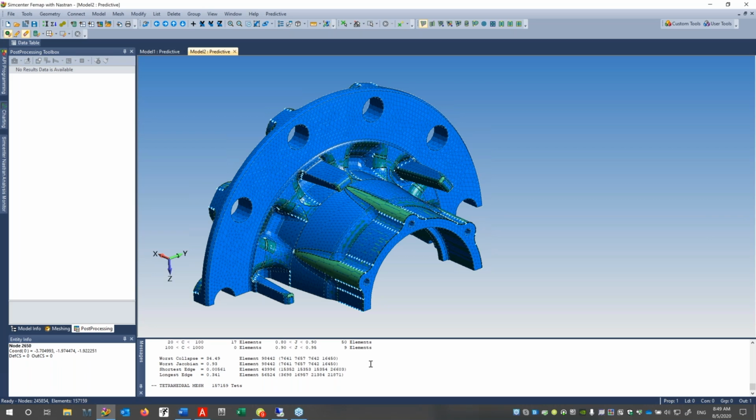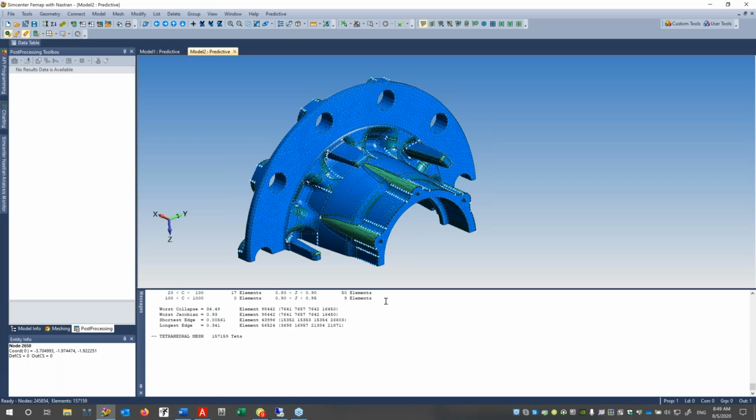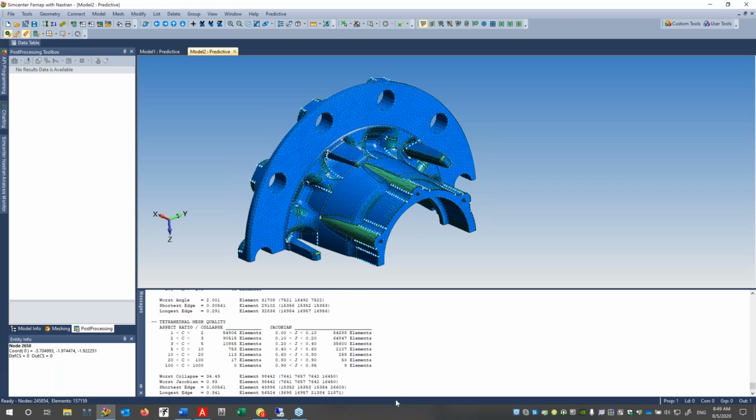And you can see it meshes, and I don't know how many people do this. It's one of those things that I started doing recently after all these years. I actually look at the statistics now. Isn't it crazy? After so many years of this stuff, it's really cool information, like how skinny and nasty your elements are.